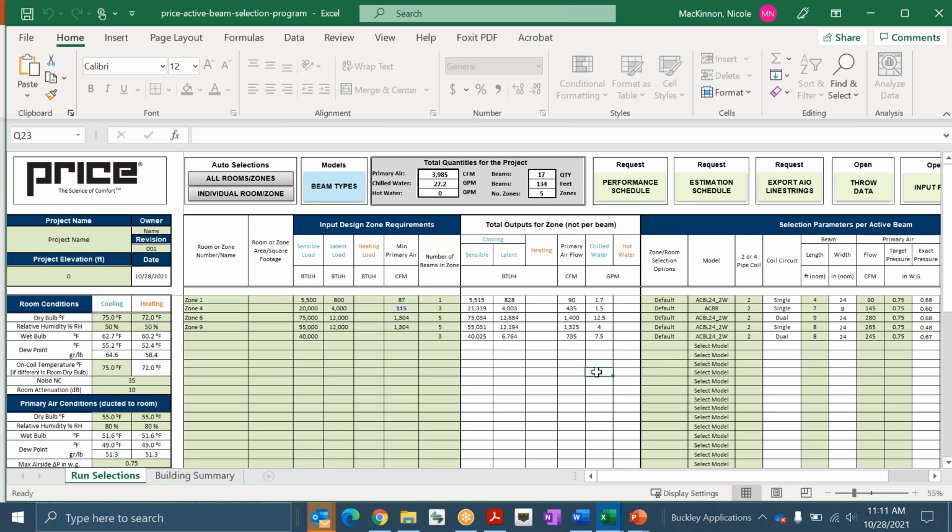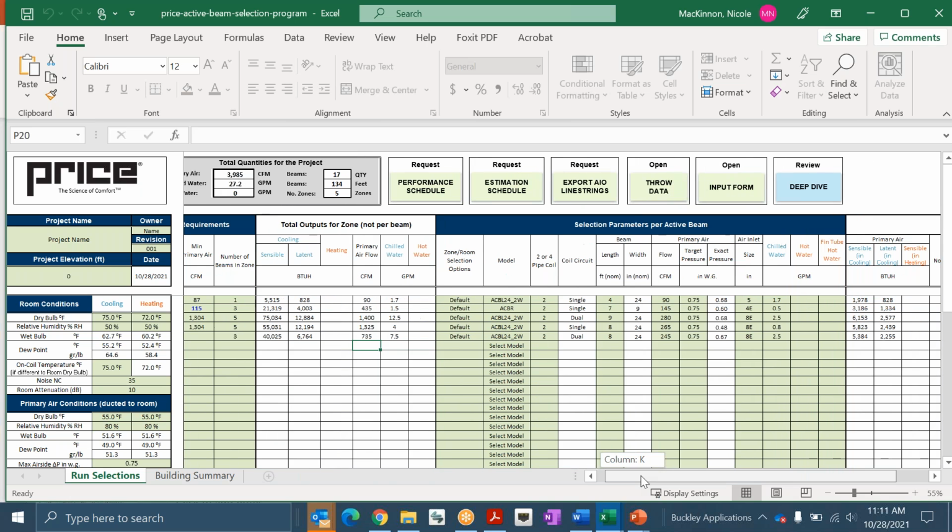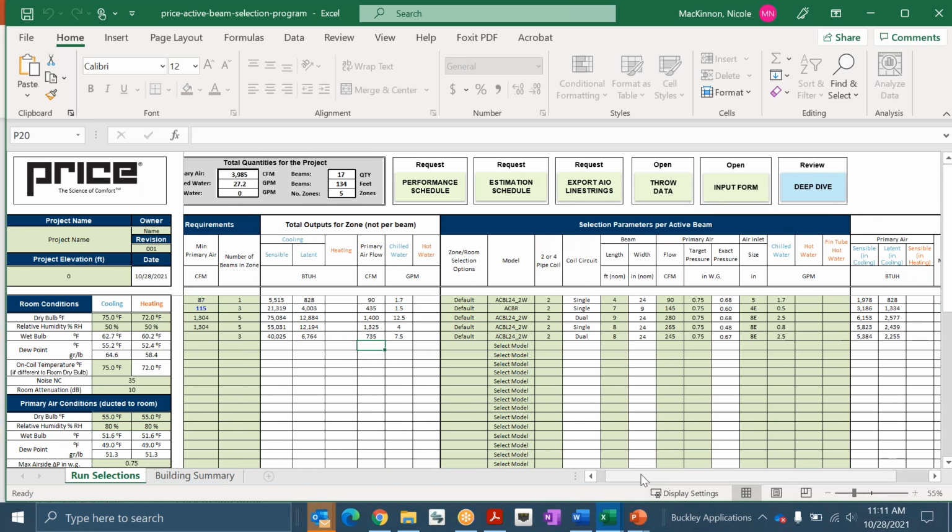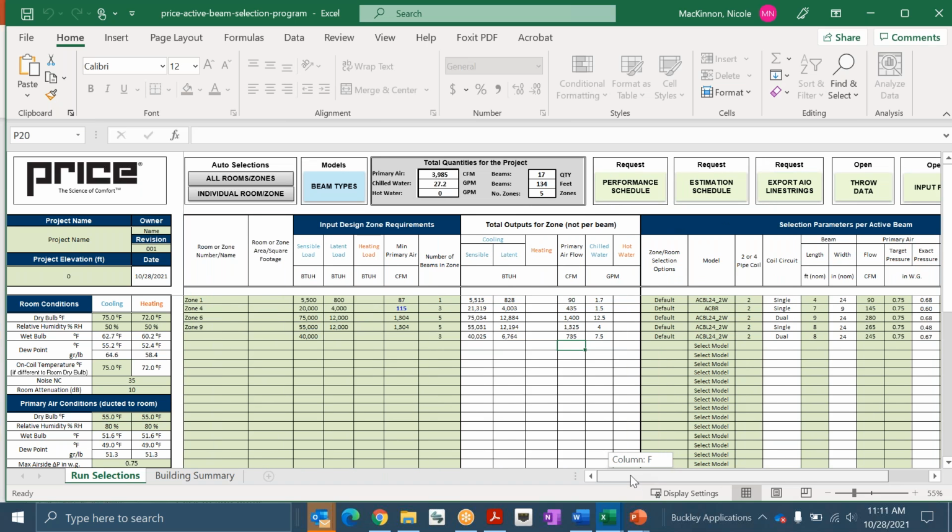And just to reiterate that point, we do like to see VAVs used with chilled beams and have some variation in your airflows, but you won't get the same swing that you would expect with an all-air system. But that is a great way to make sure you have a very efficient system, and you don't always need to be at 100% design on your CFM. You do not need to have a constant volume system. You can vary both the CFM and the GPM on the chilled beams as well.